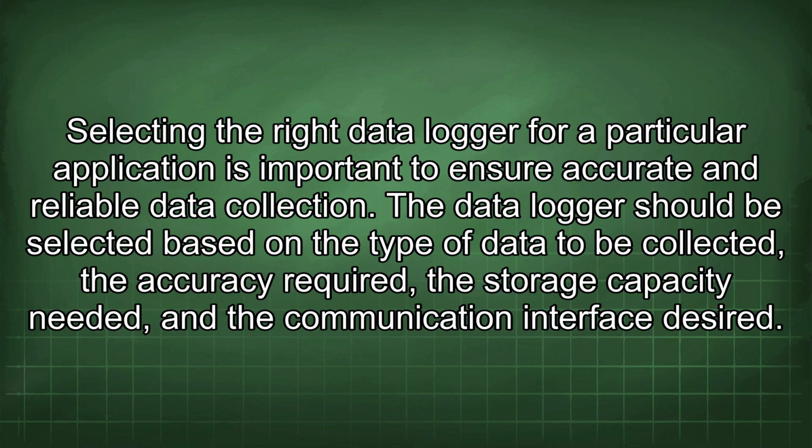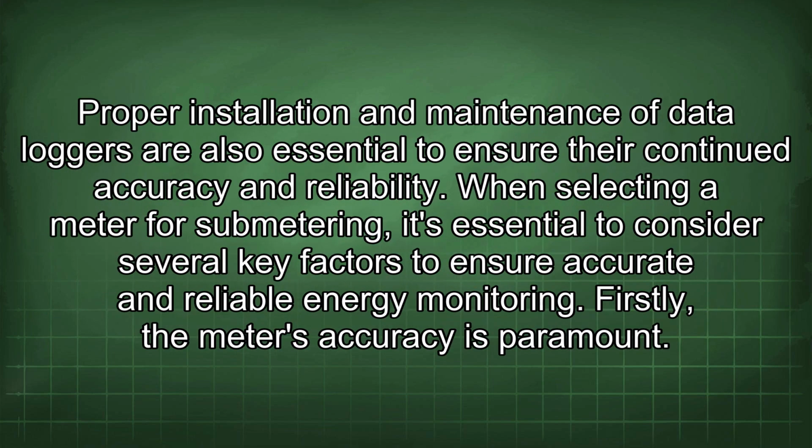The data logger should be selected based on the type of data to be collected, the accuracy required, the storage capacity needed, and the communication interface desired. Proper installation and maintenance of data loggers are also essential to ensure their continued accuracy and reliability.